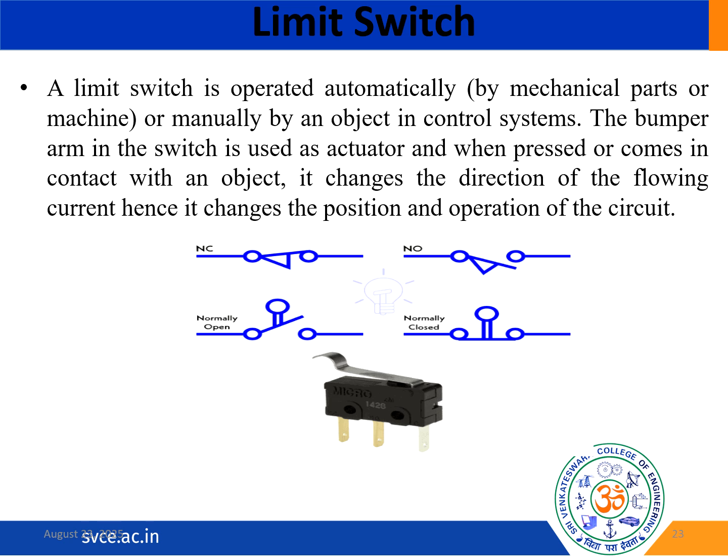Mechanical actuation is the key characteristic feature here. It can be triggered by physical contact or motion. When we consider the other characteristics of a limit switch, it ensures precise control in automation systems. Considering the discrete feedback, it is used for position sensing, and it can be used for safety interlocks.